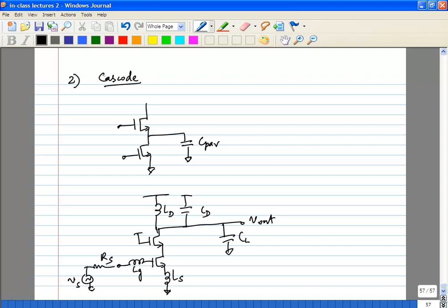And if you see, in many cases, this is probably one of the best kinds of amplifiers. We saw that the common source MOSFET has a pretty low Fmin. If you look at the Fmins you can get from this, we looked at the MOSFET 2-port parameters, right, with a common source. So you can get very low Fmins, 0.6, 0.7, somewhere around there. Even for a long channel. And now you add the cascode, you have got rid of your stability problems, or at least to some extent. Your common source has a lot more gain. So this is pretty good.